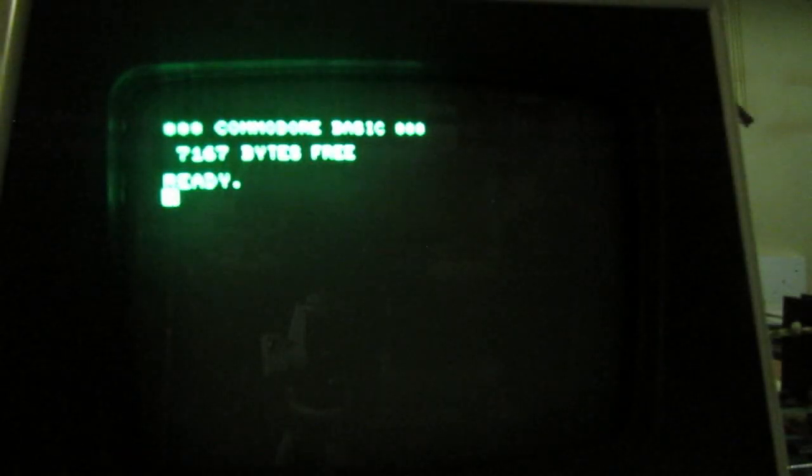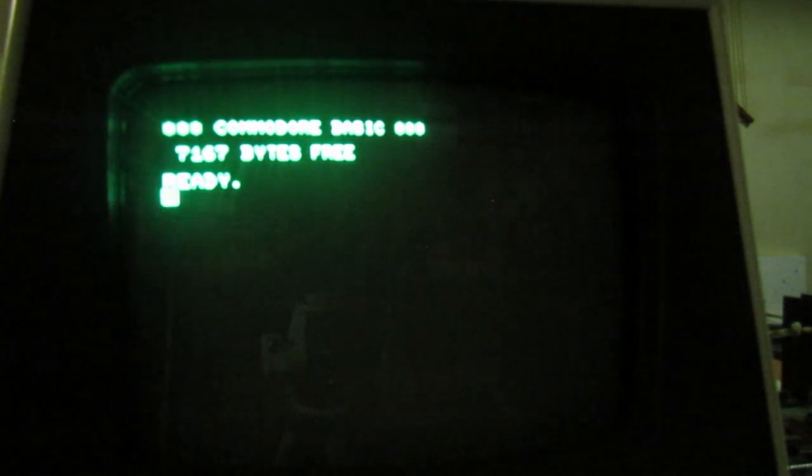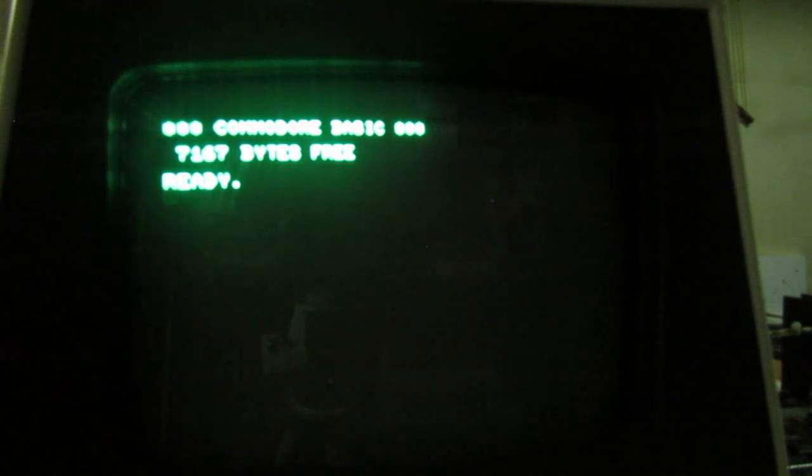So after all, I decided to try the 8.2 volt zener diode, which is different from the previous one, because the difference between the 100 nanoamp voltage and the nominal voltage was smaller than the 9.1 zener, and so I think what matters is not the actual nominal voltage, but how sharp the transition is. So let's see if I'm right and try to power off and see what happens.